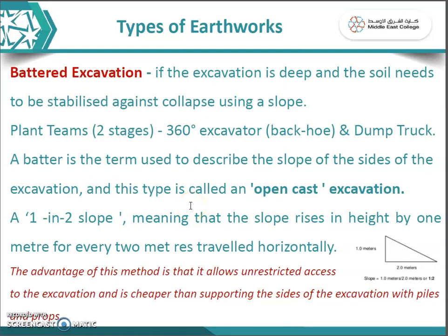Now coming to battered excavation. If you see the types of excavation, battered excavation is also called deep excavation. It comes under deep excavation when the soil needs to be stabilized against collapse. Deep excavation is not exactly straight excavation, so it has a batter, meaning a slope, to avoid land collapse. If you excavate vertically, there is a chance of land collapse, and there might be accidents at site. That is the reason they excavate in a sloped direction.